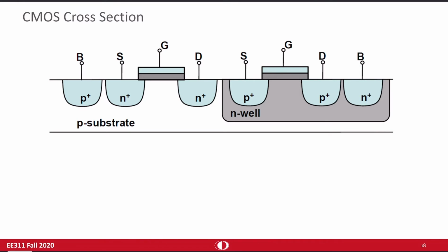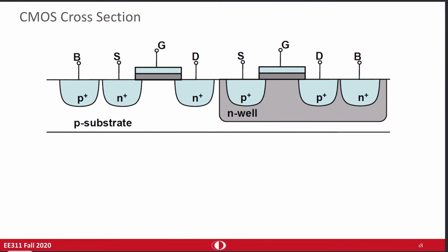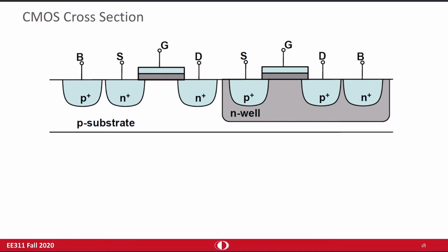So this is the cross-section for CMOS, complementary metal oxide semiconductor. This is again extra knowledge, but I just wanted to show the cross-section of a standard MOSFET. For NMOS, if you want to keep these two diodes off, for example, you connect this node to here, or the most negative potential, whichever you choose. For PMOS the directions are different, so for that purpose you connect this node to either the source or the most positive supply.